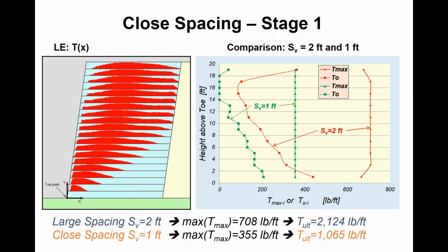I think we all feel pretty confident that the current AASHTO approach is pretty conservative, but in some cases it might not even be adequate, especially for connection loading. We're losing some information for a designer to make an informed design. So this approach is based on statics, on physics. People hopefully trust their slope stability analysis when they run Slope W or RocScience or whatever it might be. They trust their analysis. This is based on the same physics, and it's based on a strength limit state, which is often the most conservative limit state that we have.